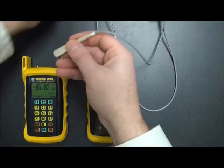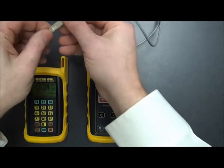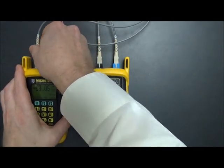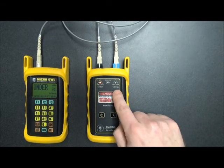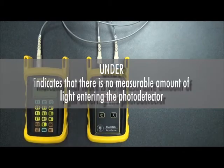What we do is we disconnect it from the power meter, and then we plug the 1300 port in. Okay, now you can see that it says under here. This is because there's no light coming in from the 1300 port. We haven't changed the wavelength yet. What under means is that there is no light coming in. It's complete darkness to the power meter.